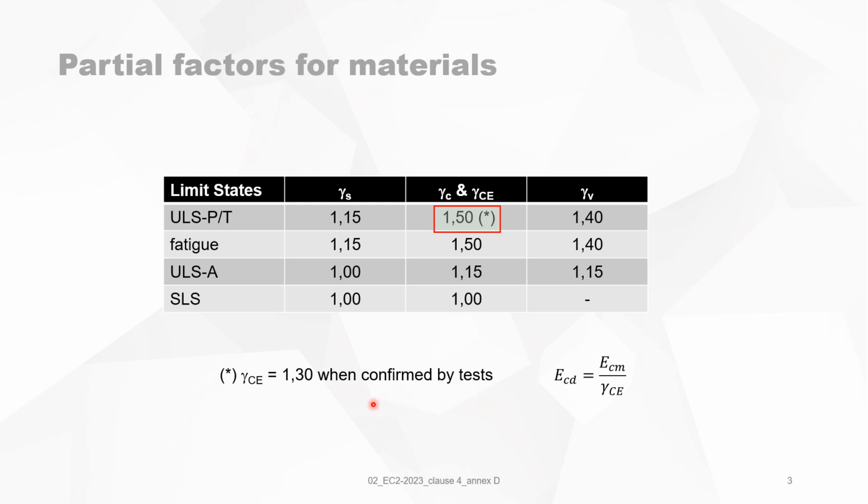In a design phase, that's difficult to obtain the needed information to apply this rule of 1.3. That's for big projects. At least when the concrete quality or composition is known before you've done the calculations, you can lower this material factor.